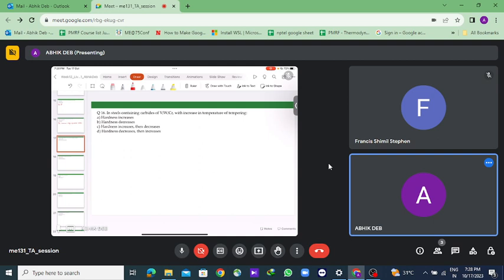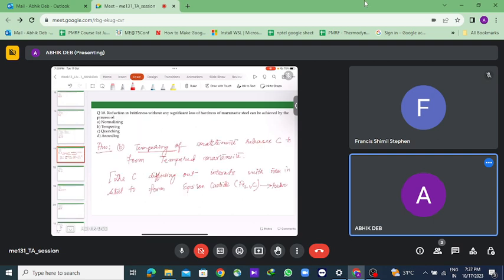It is not Fe3C, it is called epsilon carbide, that is Fe2.4C. Okay, it has reduced lattice strain. Since the lattice strain is reduced as compared to when it was a BCT structure, the brittleness will decrease.